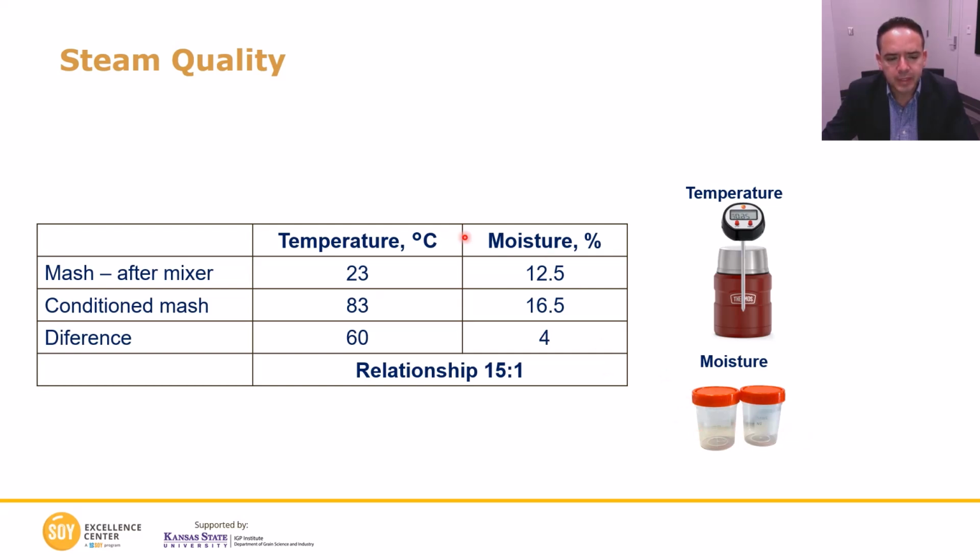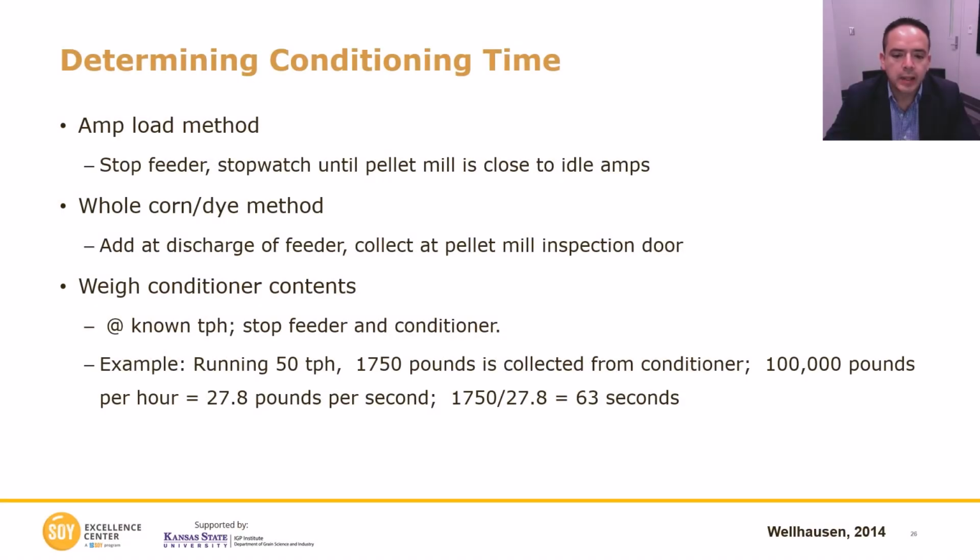So this data, as I mentioned, is good to evaluate the quality of your steam. However, when you are collecting these samples, you need to be very careful. Use an insulated container, and for moisture, you need to seal and cool down the sample before you analyze it. Now, I am going to show you 3 different ways to evaluate conditioning time.